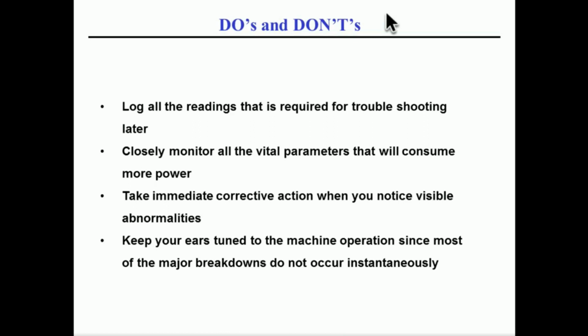At least when the discharge is high or the compressor is making noise, you can try to bring down the capacity so that it runs at an optimum level till you take corrective action. Keep your eyes tuned to the machine's operation, since most major breakdowns do not occur instantaneously. It generally starts with a smaller thing, then it aggravates, and ultimately it leads to failure.